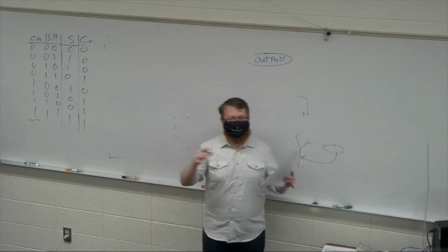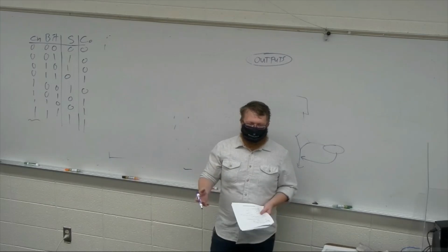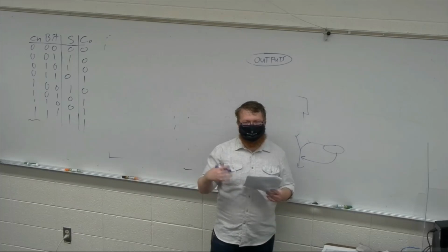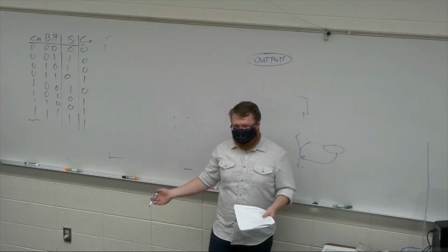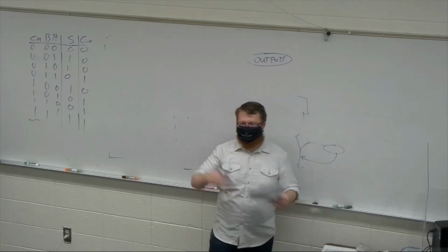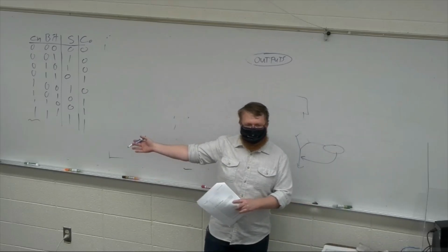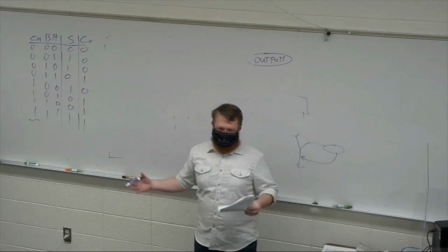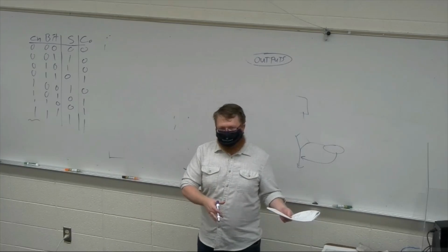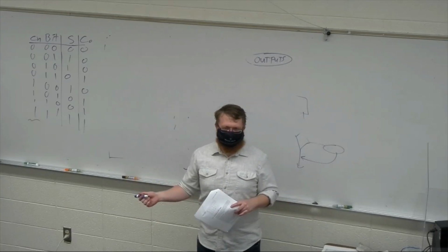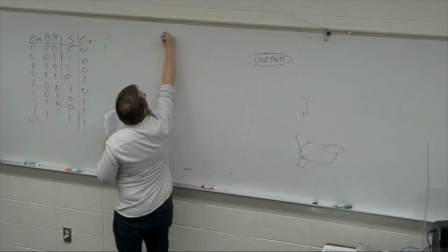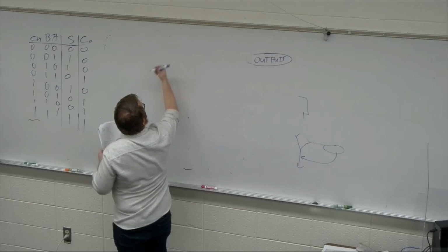So there's two different things that we think about when we design an FPGA. The first is data path. What you guys are working with so far is mostly data path. You're doing something with the data. Eventually, you'll have to build control logic that decides, am I working with switches, or am I working with the ROM? What am I doing with the data A? And so this is the decision matrix. This is going to be a description of the decision matrix for the add or shift in that add shift multiplier.